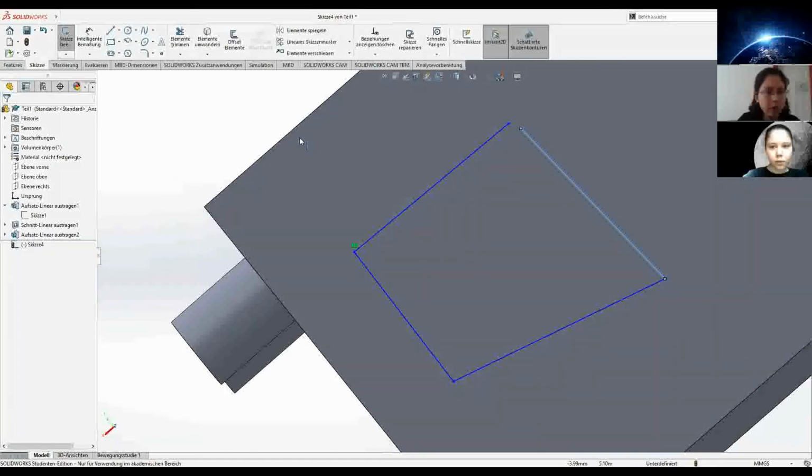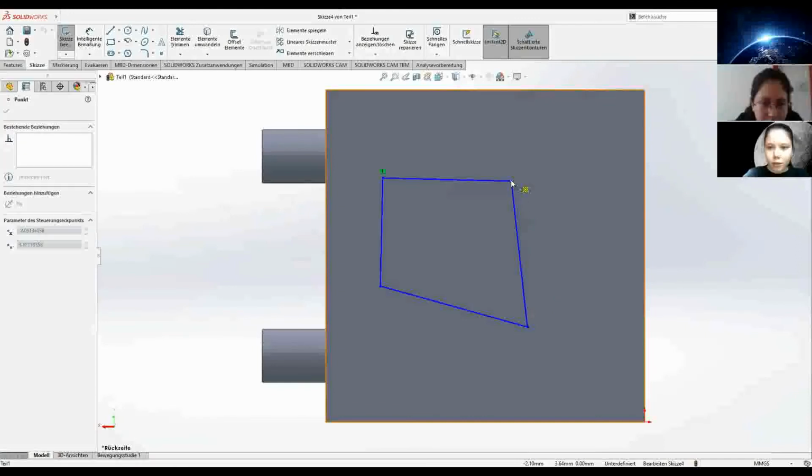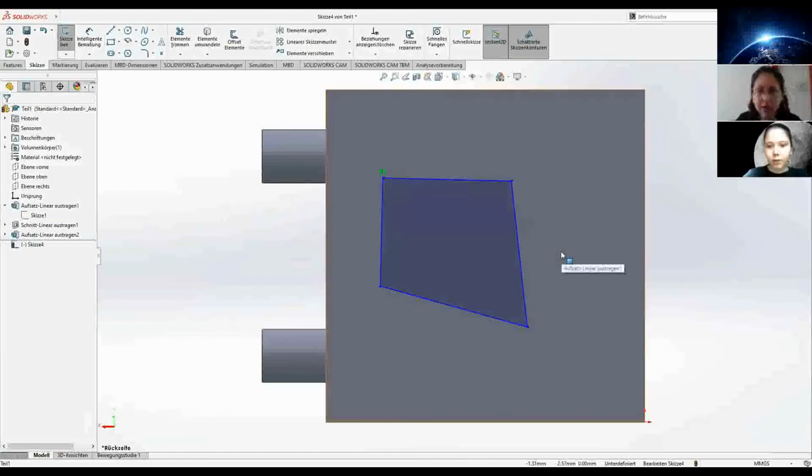Okay, so can you get also the normal view, please? Always try to work in your sketches in normal view because if you're in another view, then you'll see your sketch deformed and then you'll have trouble also. Okay. So yes, you can also drag it. Perfect, yes. And you see how it changed color to a dark gray color? So it's a closed contour right now.